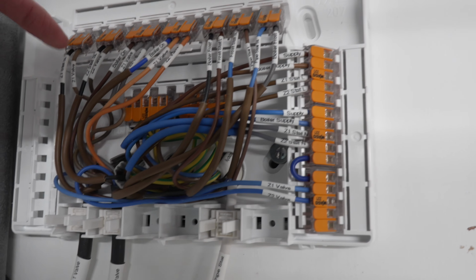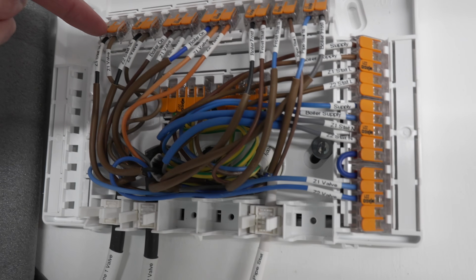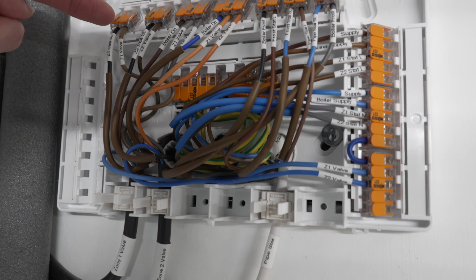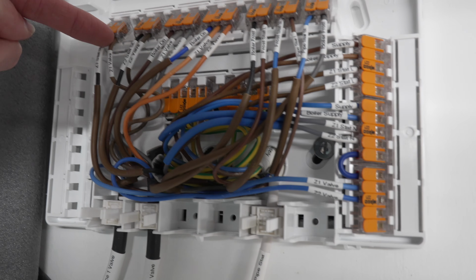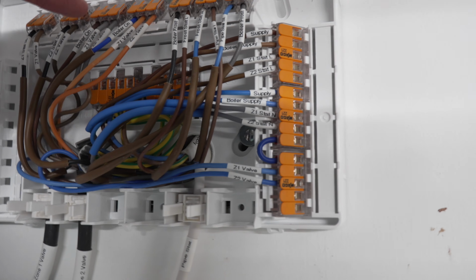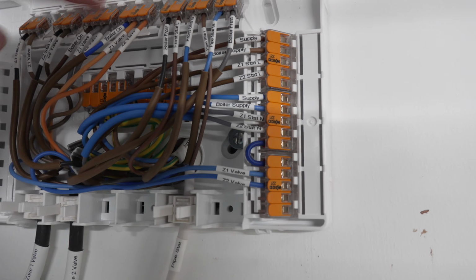And then we can see we have the switch wire that comes from the thermostats connects to the brown wire of each valve. So when the thermostat turns on, it powers up the brown wire of each valve, and that causes the valve to open. That valve opening causes the switch to close, and that connects the boiler on signals together.